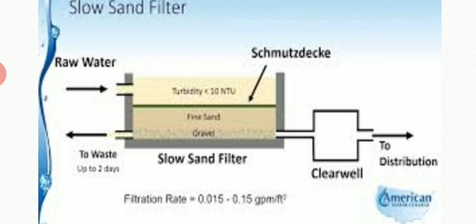So the green layer you are seeing will earlier be reddish brown. That is the impurity settling on top of fine sand, rich in partly decomposed organic matter, iron, manganese, aluminium, and silica.